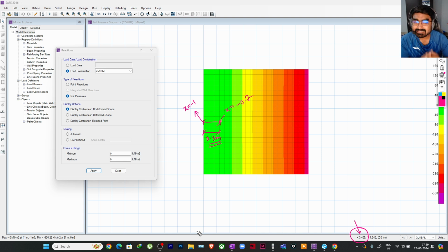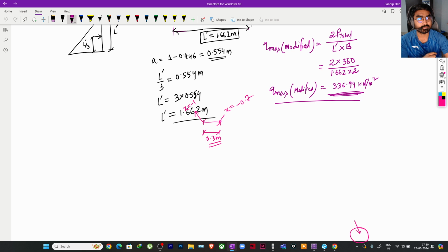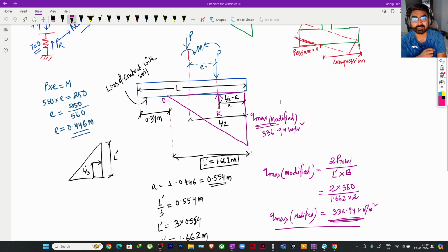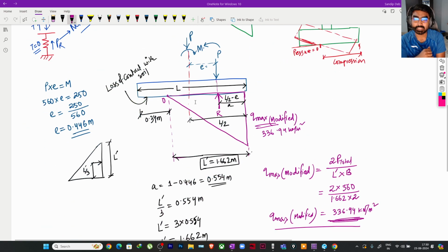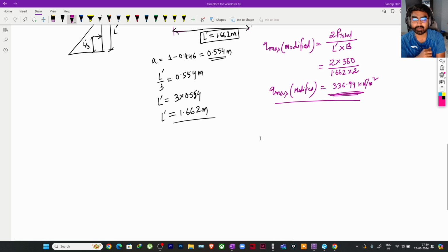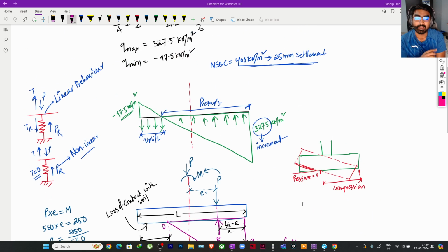So this is how you can analyze a foundation under uplift for eccentricity along one direction. Eccentricity means that we have calculated the equivalent eccentricity and load product to convert the moment into P times eccentricity. So if you have uplift along one particular direction due to this uniaxial moment, you can use this method to check the software analysis manually. And I'm talking about an isolated foundation.